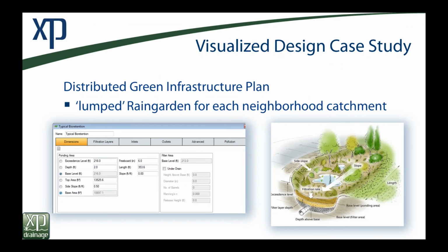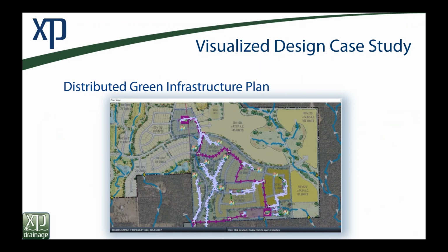We really just had the dimensions, which were almost completely automated for us, and I just used the same filter media depths and layers everywhere. So you just throw these together. We can see a big picture of how the drainage system looks. Ultimately everything drains to the pond, but before it gets to the pond, within each catchment there's a rain garden and there's treatment. There's still that untreated portion of the site leaving on the left side.